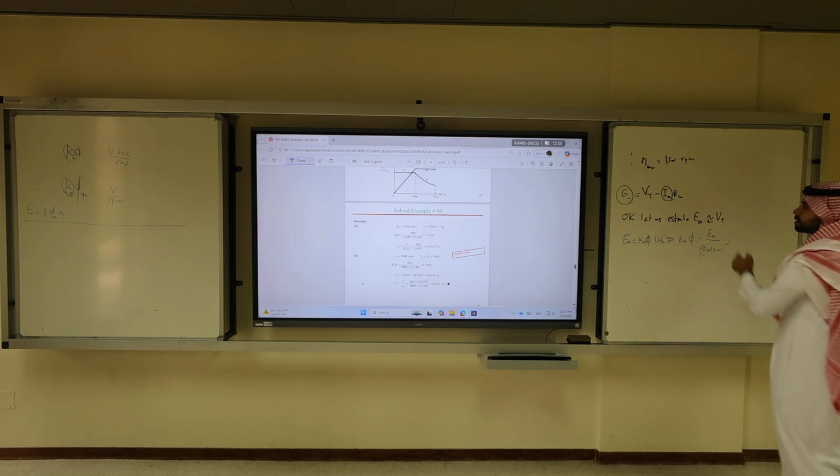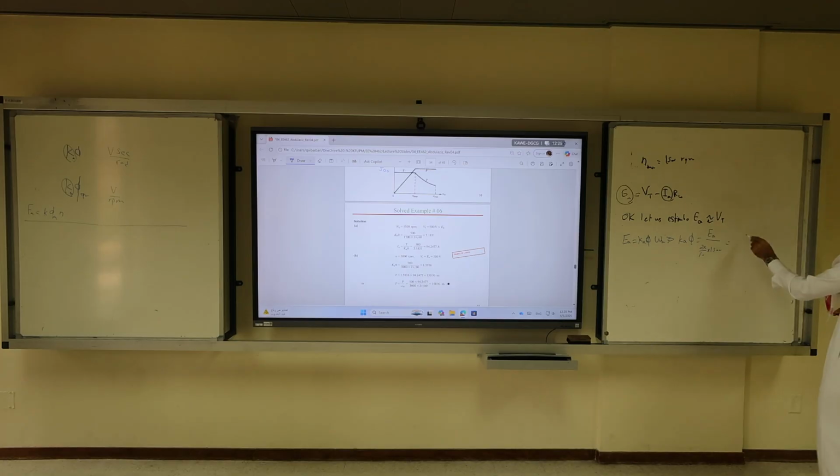So what is Ea? It is Vt, which is 500. So 500 over 2 pi over 60 times 1500, you get 3.183. What's the unit? Volts times second over radians.